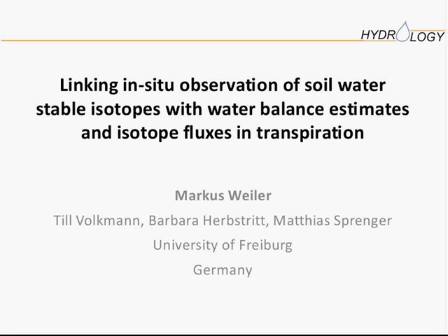So you may already have seen this paper. I just briefly go over it. That's a new method we developed to continuously measure stable isotopes in liquid water using this Membrana micromodule. It's a module that has been used a lot in GC analysis, and we just set it up so we have on the one side a stream of nitrogen to the Picarro in this case, but as you know, you can use any kind of laser spec instrument.